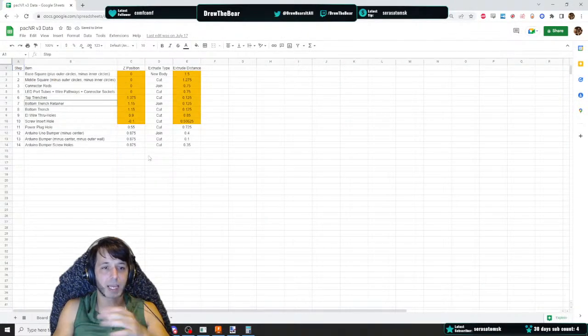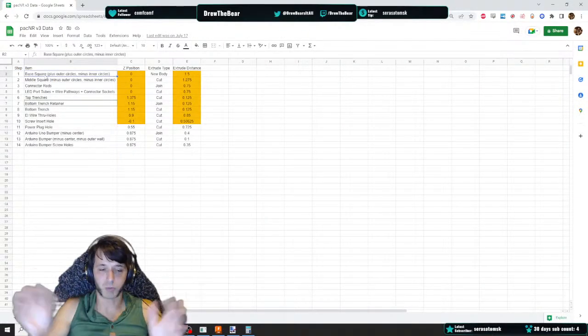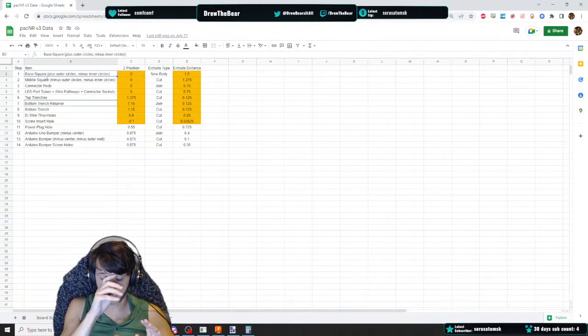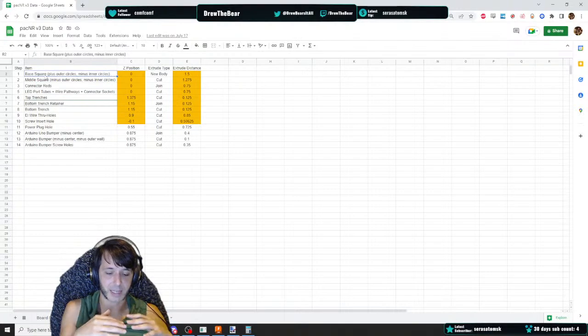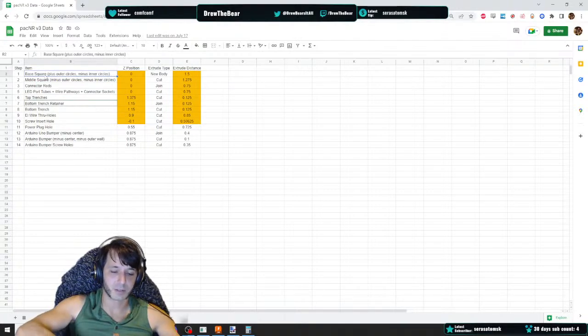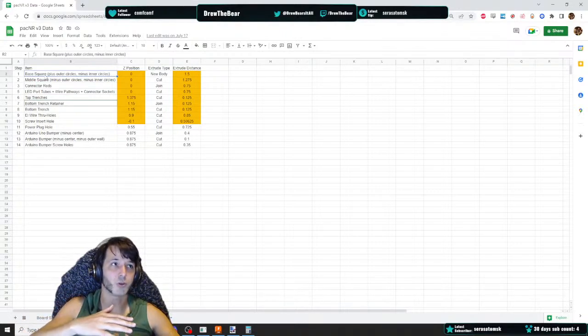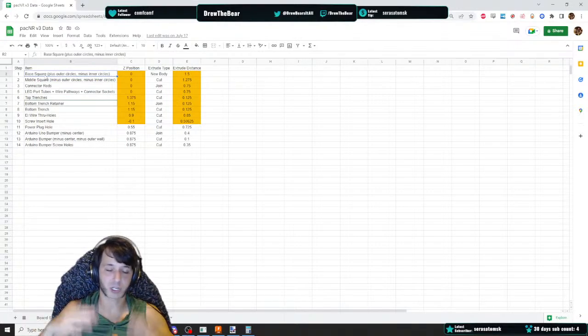Model extrusion. So we have a base square, which is just the whole bottom piece. The way the 3D models work with extrusion is that you basically just say, hey, take this object and expand out from that position into 3D model space. And then you can also say expand that area but cut anything you hit instead of joining it to the current model. So we make a big square, then we start cutting into it. We make it like a rectangular prism. We just start cutting into it. And that's how we build what I have here.